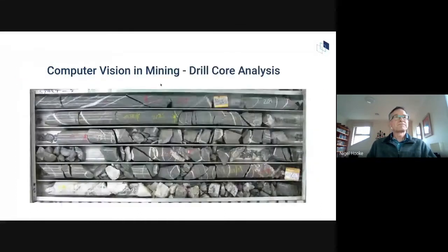Next slide, please. So typically, this is what the geologist is presented with. This is a wooden tray with sections of the rock laid out in consecutive order as they were extracted from the drill. You can see that the rock changes a bit as you go down, even over a matter of a couple of meters. Some of the bits are quite clean and hold their integrity. Others are fractured into lots of pieces. There's a couple of wooden cubes there with some felt pen writing, where the person who was laying the rock in the tray has made some annotations about the depth or what happened when that piece broke off as it came out of the drill.